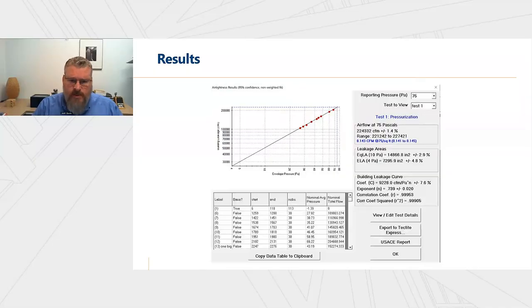You will see them bounce around a little bit. This data is exceptionally clean. It doesn't always look like that. There are some numbers in the middle right. You'll see correlation coefficients R and R squared. Those have to be above a certain threshold, depending on the test standard, basically determining that the data you have is good enough and meets the accuracy requirements that have been determined through research.